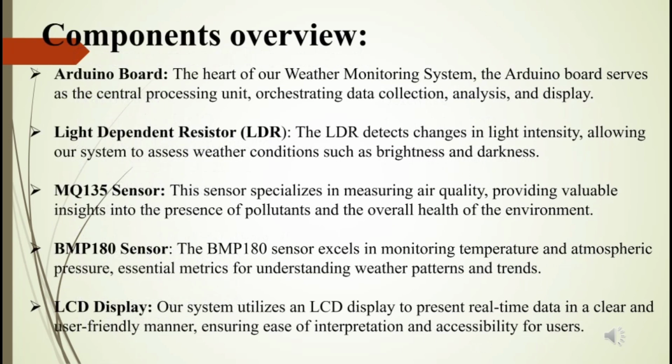Component overview. Arduino board. The Arduino Uno which we are using for this weather reporting system acts as a central processing unit which helps in data collection, analysis and display. Light dependent resistor. The LDR detects the change in the light intensity, allowing us to assess the weather condition like brightness and darkness. MQ135 sensor. This sensor specializes in measuring the air quality, providing valuable insight into the presence of pollutants and the overall health of the environment.